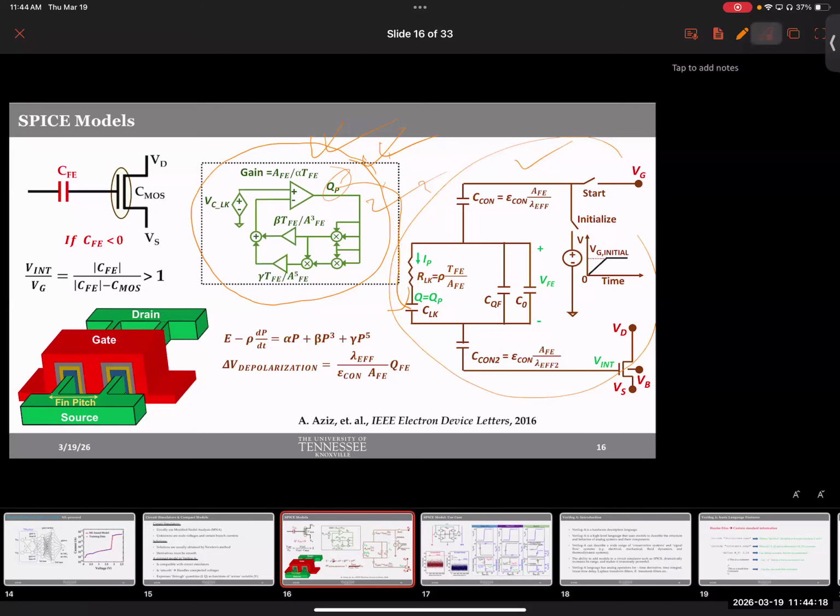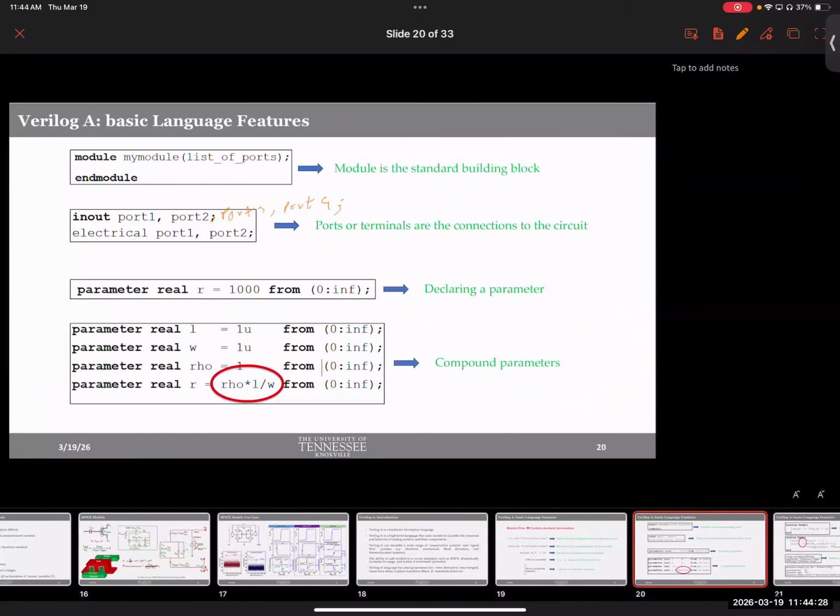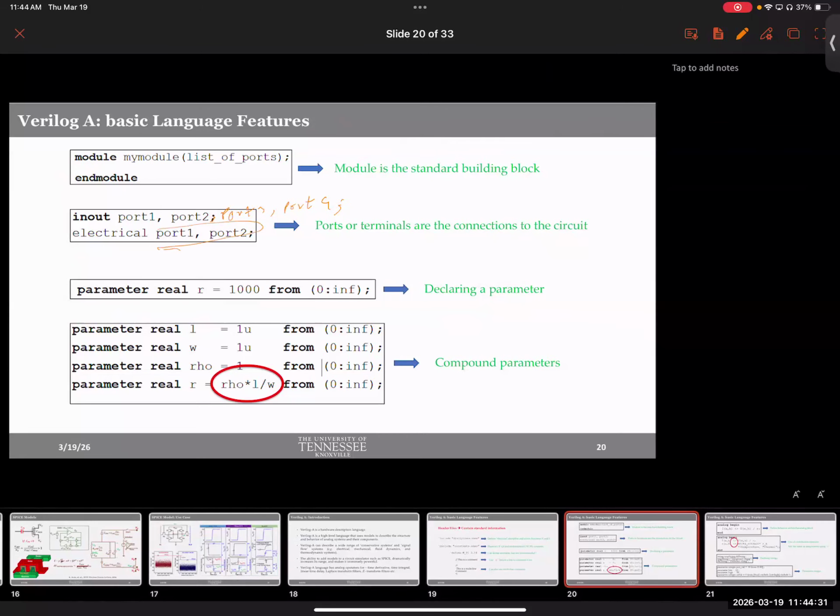How do you solve KCL? Right? So you get errors from circuit simulators, unless you mention which of these ports are not electrical ports. They're supposed to be intermediate ports. Okay? So for this example, both our ports are defined as electrical. But when you have extra ports, you don't define the others, the virtual ports, as electrical. So SPICE only treats these ports to solve KCL and KVL.